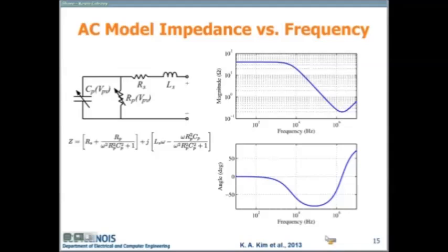We are left only with the RS. Everything else cancels out except for the series resistance. So if we can measure this point approximately, we can get the series resistance pretty accurately. The second part is once we go above that, we see the inductance characteristics start to dominate, because it's stopped acting as a capacitor. The capacitor is here, resonance point, and then inductance parameters start to take over.